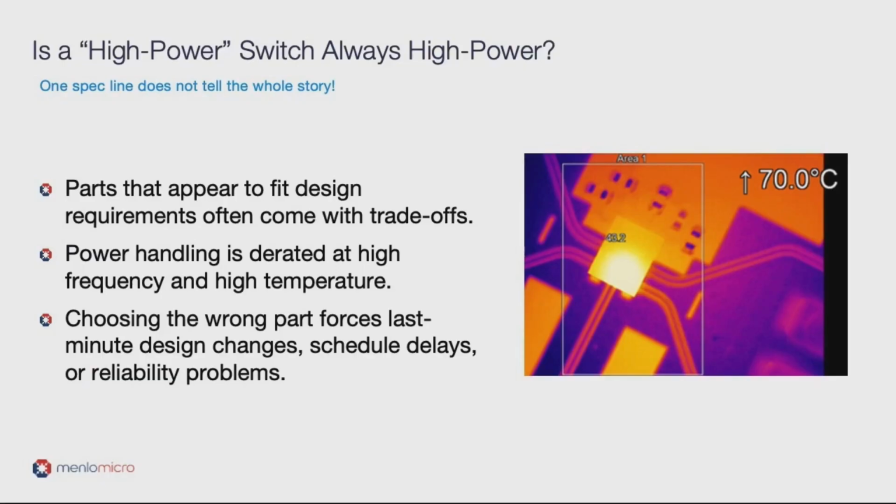Now, those upper limits I mentioned earlier are often only in ideal conditions. As a designer, taking a quick look at a switch datasheet, it might imply that the part's perfect for your application, when in reality, it comes with a lot of trade-offs. Many switches only reach their advertised power handling at a lower frequency than their advertised maximum, or only at room temperature.